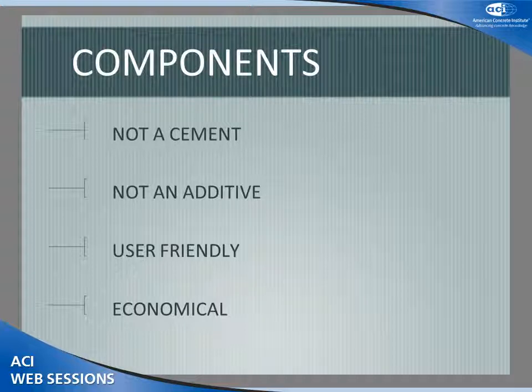Now, here's revolution number 2, the components, breaking it down. A component that, when added to a standard concrete mix, produces a shrinkage compensating concrete has been available and in use for approximately 4 decades. But the product has never been able to establish wide acceptance, and it's understandable since it was not included in, nor in compliance with, ACI 223, and therefore it lacked the credibility and the weight of ACI recognition, acceptance, and documentation.